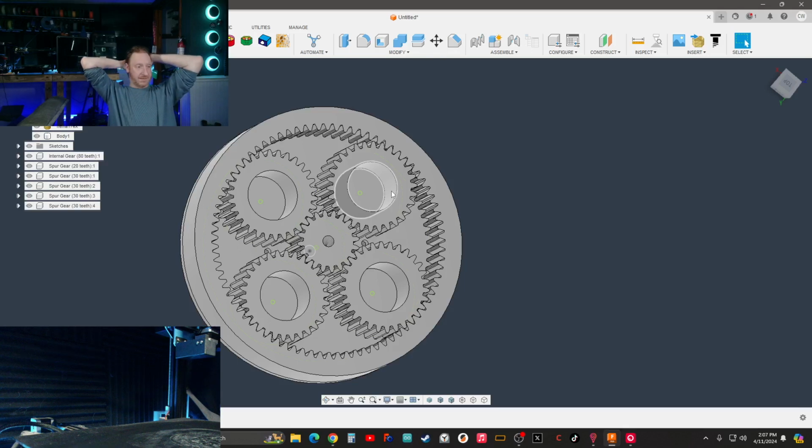We also have to put an encoder in here. Well, no, we don't have to put an encoder in here because we're using a stepper. We can just count the amount of steps through the code itself. But we would have to have a homing switch on here. Not homing.